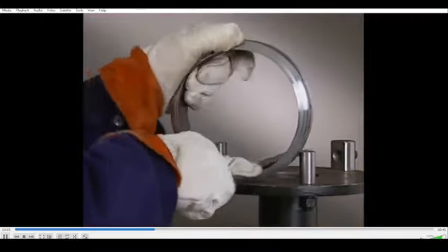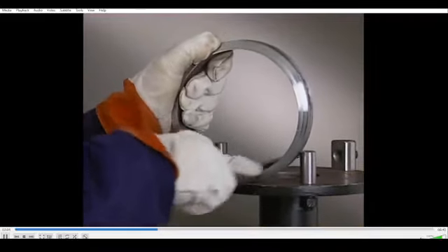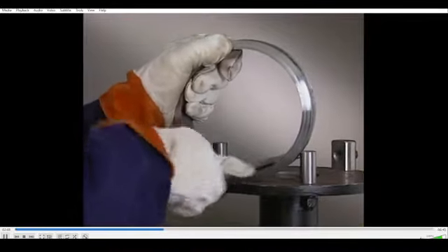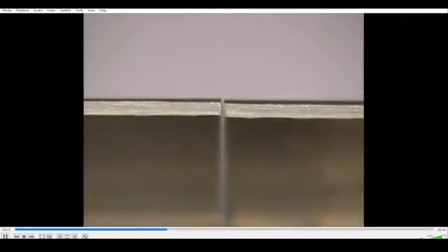Cleaning, filing, or some grinding may be needed to remove contaminants or burrs from the weld area to provide a consistent root face. On pipe wall thicknesses of 1/16 inch or less, the edges of the joint are placed together with a zero root opening. In some cases, filler metal is not used, and the edges are welded together autogenously.